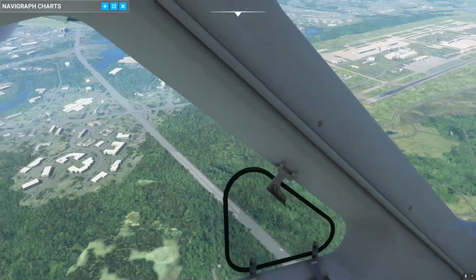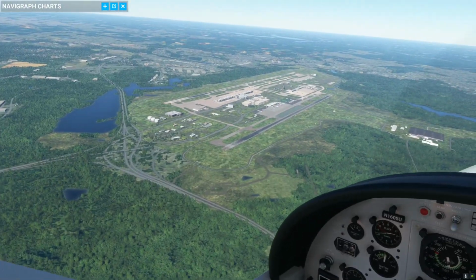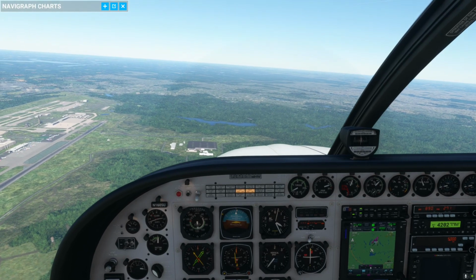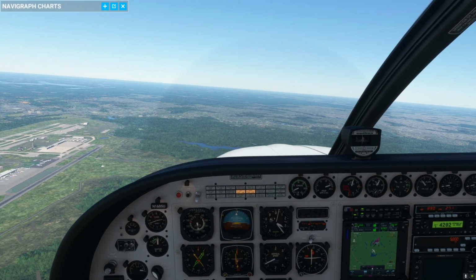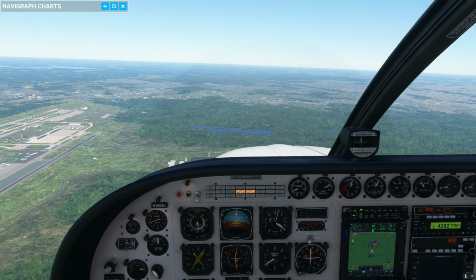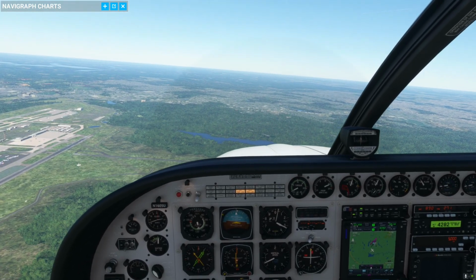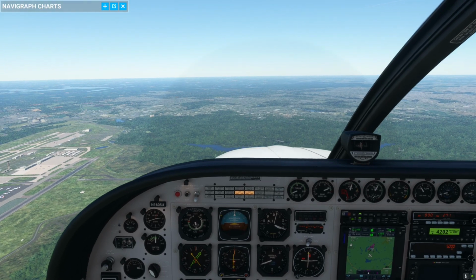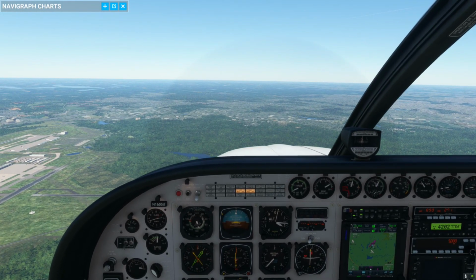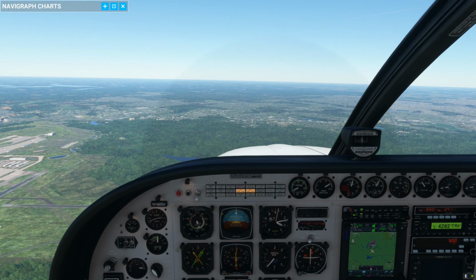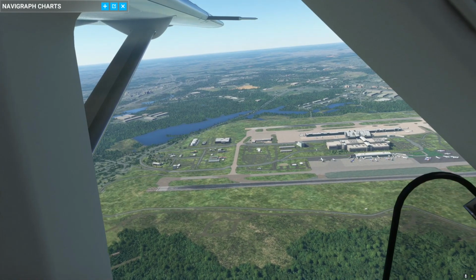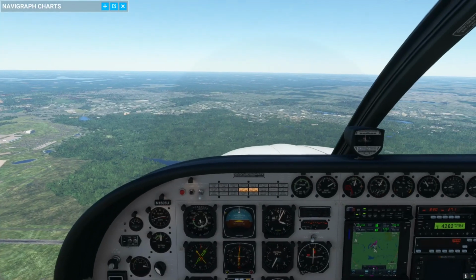So I'm totally visual now. Screw the GPS. Right now we're just dropping some flaps. Drop power. Trim for speed. Right now we're trimming for VSI. We're just hoping. We're definitely too high. That's why power's at idle. I'm going to fly a wider pattern.